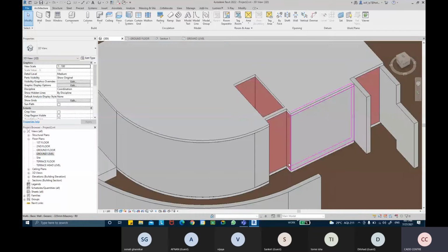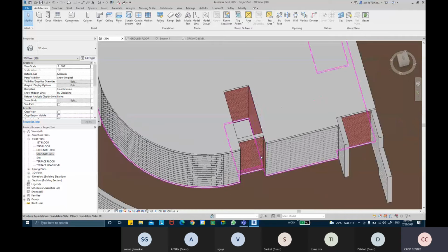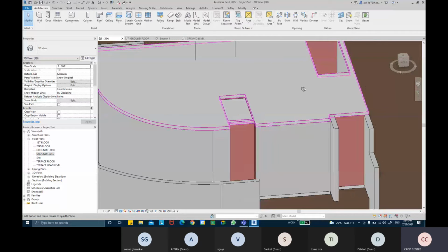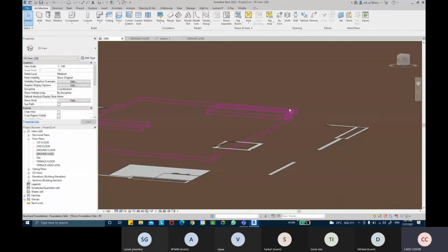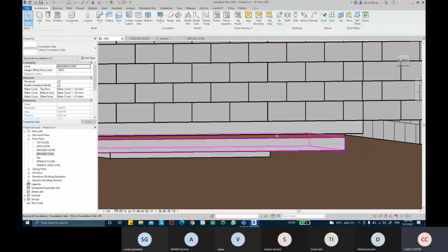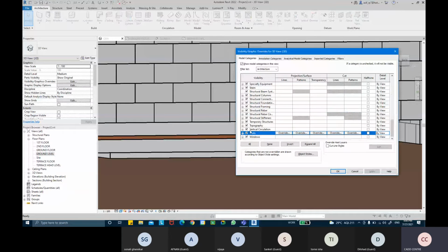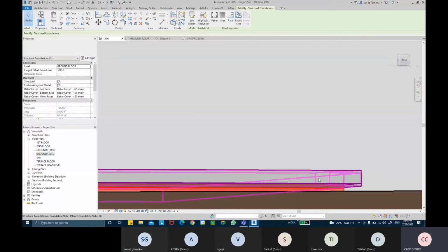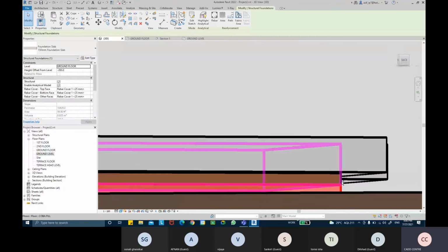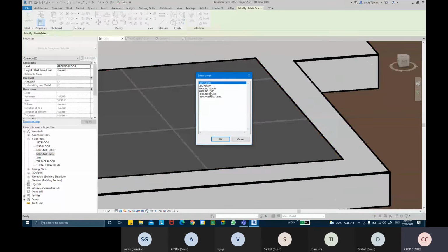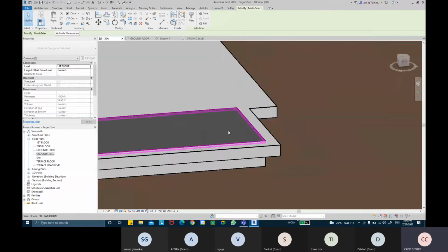you can copy the sunk slabs as well. Okay, so you can again copy that sunk slab from this level, and paste it to the first level as well. Okay, here we go. This side as well, so you can copy the whole thing actually, the sunk, the coba fill as well. So I'm going to hide these walls because they're distracting me a lot while copying. So I can now select the sunken, the coba fill and the finished floor as well. So copy, align it to the first floor as well. It's going to go over there.